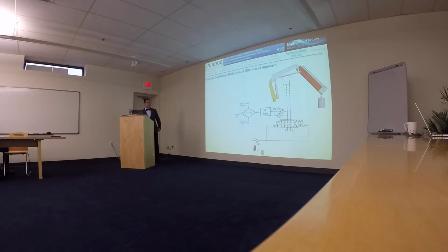So again, we have the same logic for the pressure sensor selection, and then we still have the FFT estimation and peak detection, but now the FFT estimation just gives us an estimation of the location of the oscillation and whether the oscillation actually exists or not. And so now we take the pressure and use what I implemented, these two filters and modulation, which I'm going to explain in the next slides. The result of these two filters and modulation is the output, which will be superimposed on the operator command.